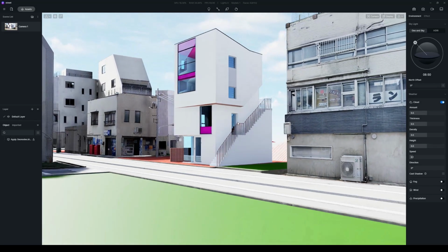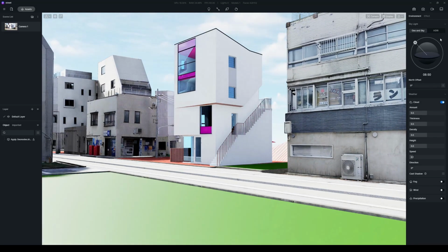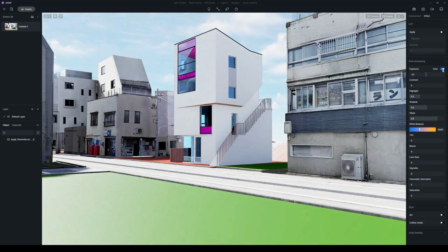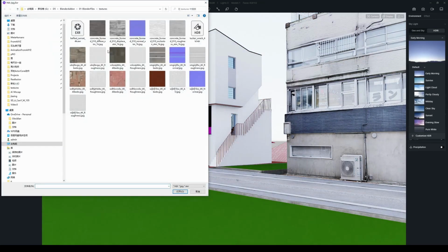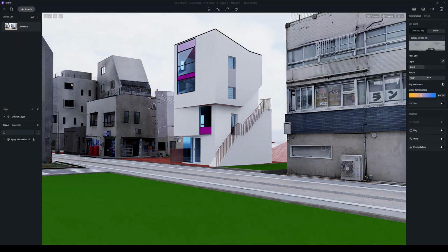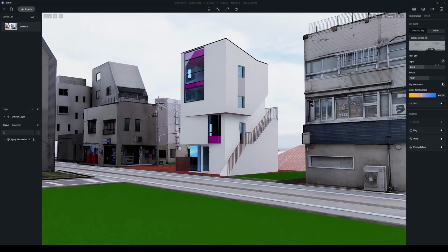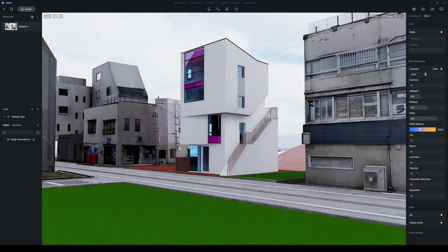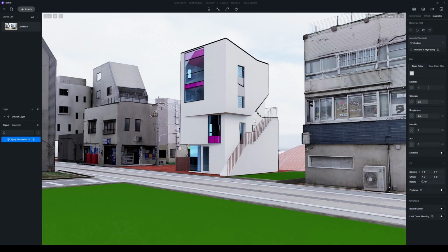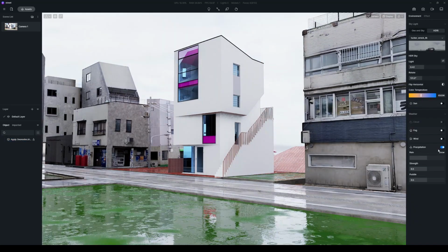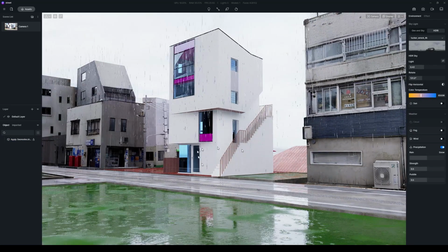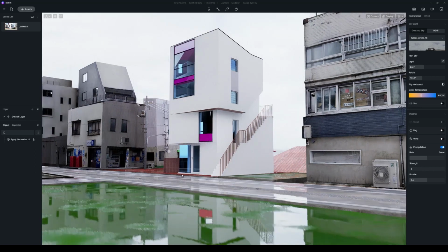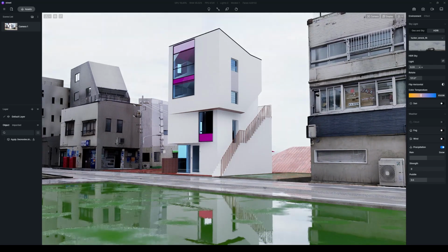Here we want the sky to have a bit of gray tone to demonstrate the after rain atmosphere. First, turn off auto exposure. Import the HDRI you need, and rotate it to a proper angle. Then adjust the sky light intensity, setting a proper tone for the overall lighting. Turn on precipitation in Environment, Weather, and adjust its strength to 0 so that puddles appear on the street. I think I've achieved the desired effect now.